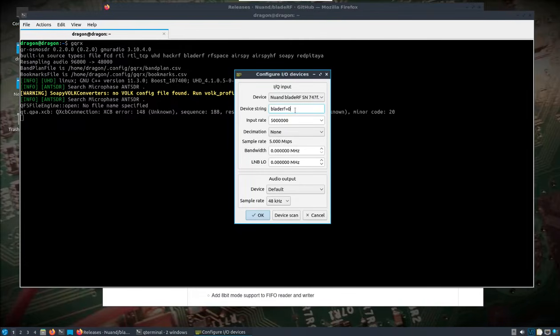Then we'll pass the additional arguments that are needed to enable this mode and really increase the bandwidth and sample rate. So sample format equals 8, and we'll do feature equals oversample. I'll manually punch this in. I'll just go with 122 megasamples per second. I'll leave bandwidth at 0, so it should just be the whole range there.